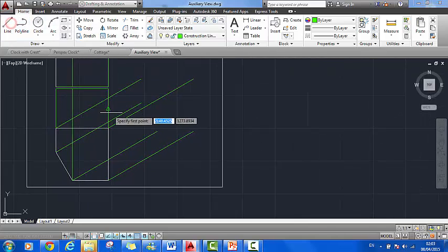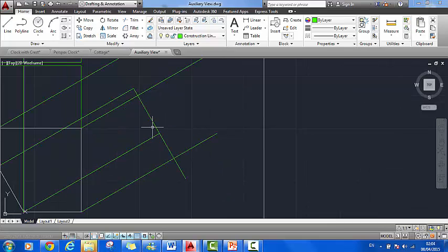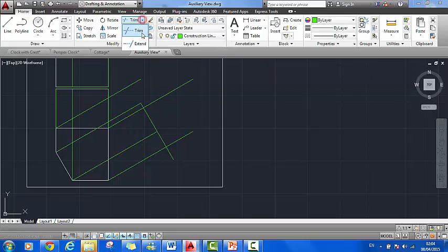I'm now going to draw in another temporary x1, y1 line. I'm going to estimate this at 100mm long, tab 60 degrees. Now I'm going to also extend that on.